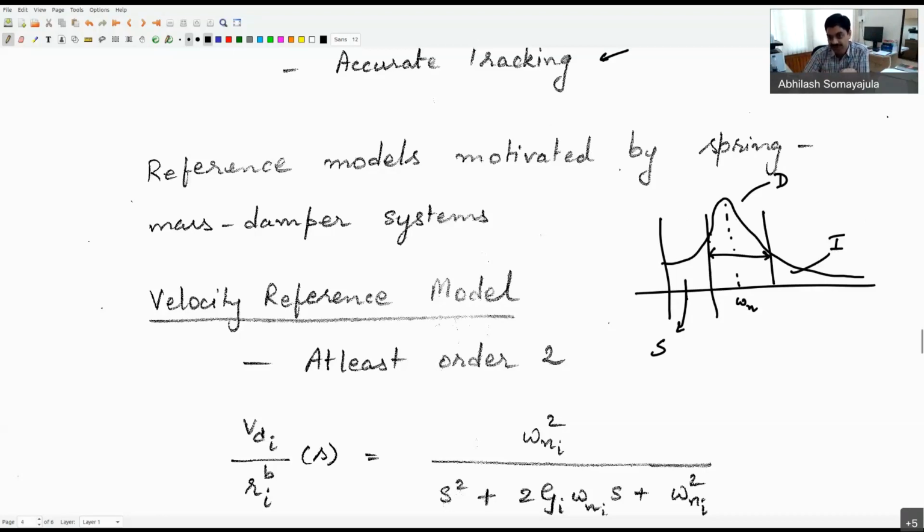So we can then tune it. It's more intuitive to tune it with a spring mass damper system and figure out how much bandwidth I want. Tuning this means finding the values of the appropriate mass, damping and stiffness, or I might call it in terms of natural frequency, damping ratio, things like that, based on which I can adjust how it actually looks.